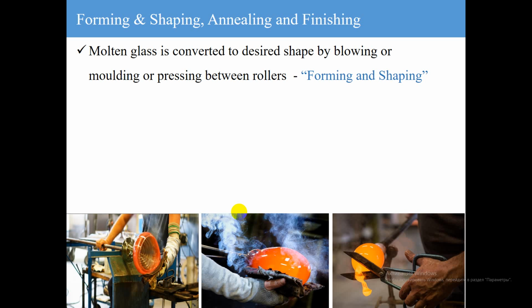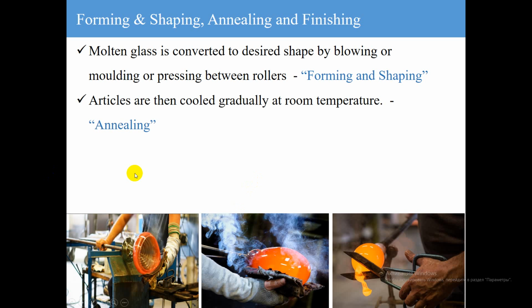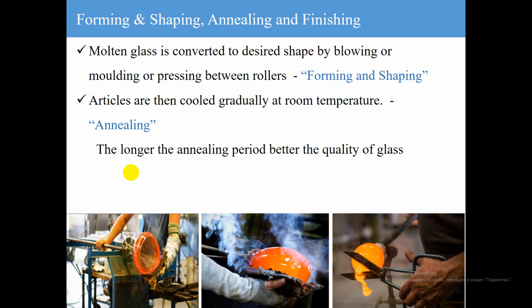This is forming and shaping. Articles are then cooled gradually at room temperature. This is annealing. The longer the annealing period, the better the quality of glass.